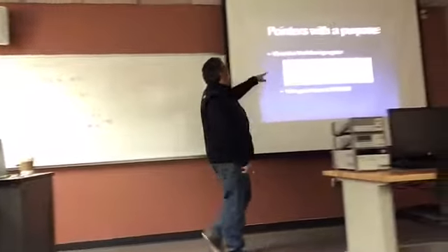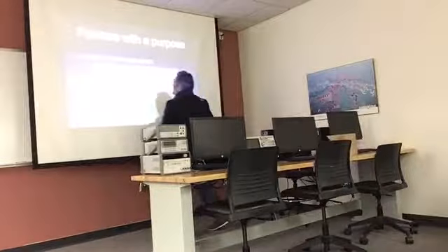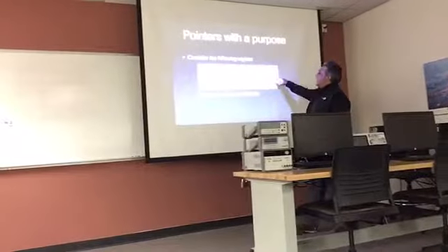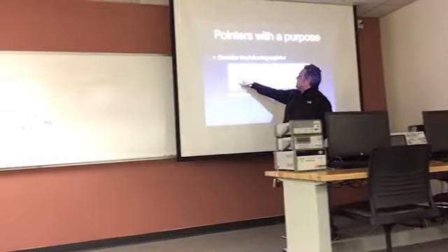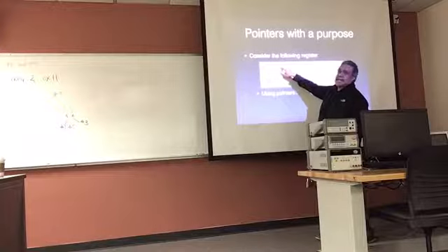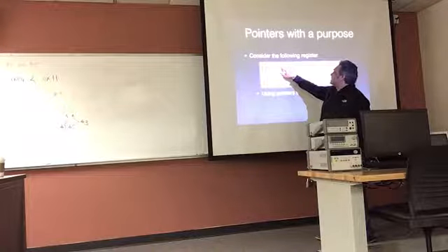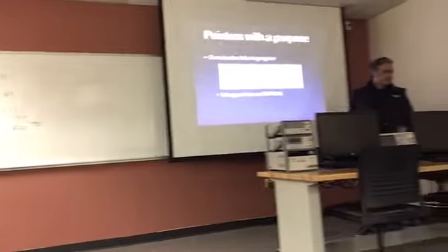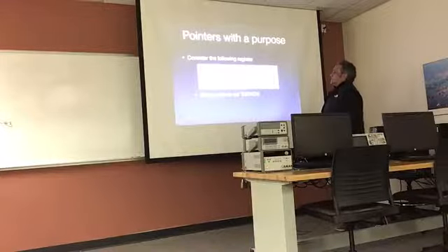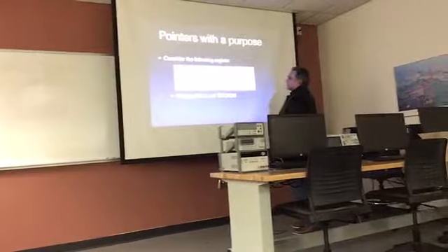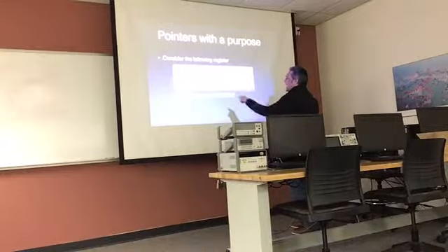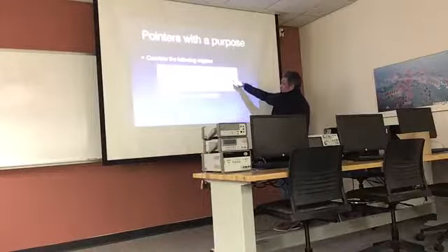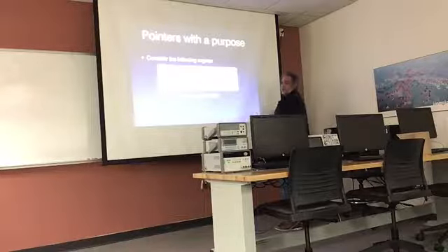So this particular circuit is for a timer called timer 1. That's how the register is built internally, and this guy is the name of the circuit. The circuit is called T1CON, timer 1 control. That's really what it means, okay? So, using pointers, I want you to set the circuit called TMR1 on.